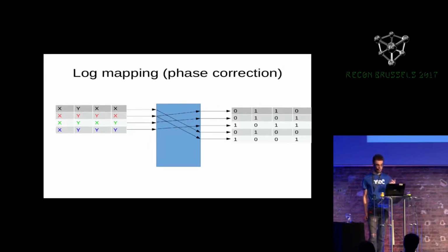So as we're toggling, sometimes the bits can be active high, active low, hard ones, hard zeros. So this is a way to find, if you toggle from all X's to all Y's, you can see the phase of your bits and then move on to do the actual mapping.